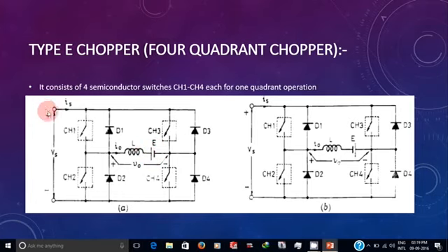The reason is the voltage supply will be made to flow in this direction. Hence, consider a motor where EMF will be produced opposing that supply. That is the reason behind that polarity. In the third quadrant and fourth quadrant, the supply will be made to flow in this direction. Hence, the polarity of the EMF is made like this.